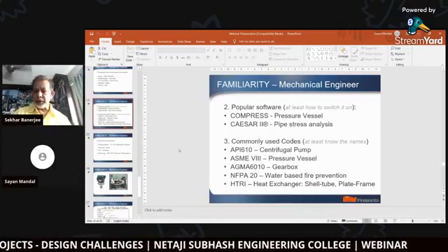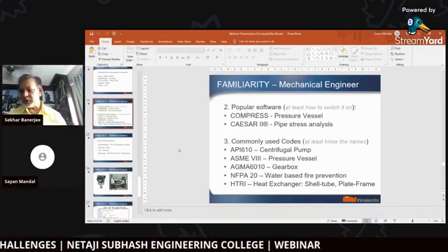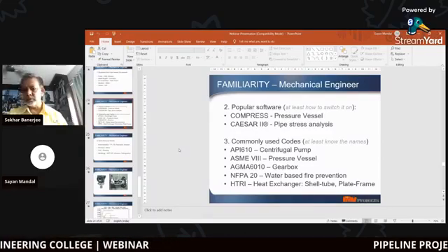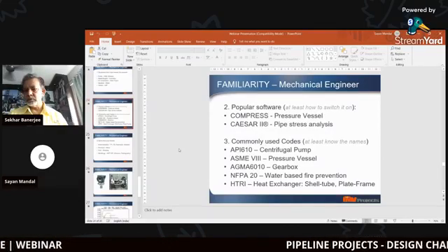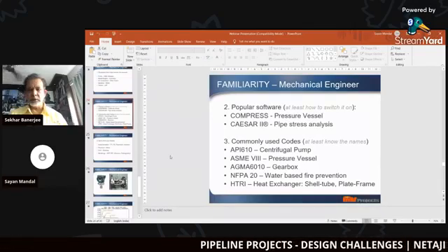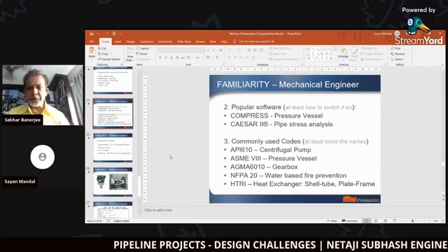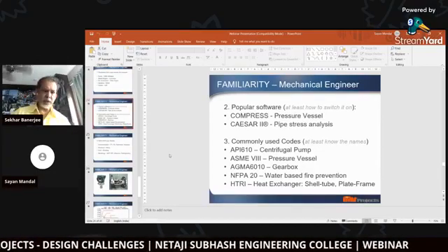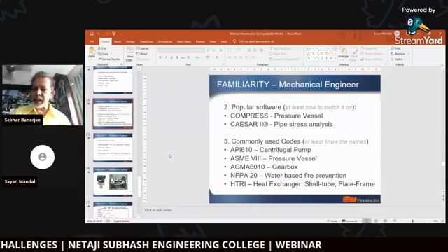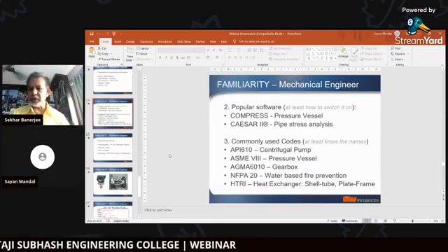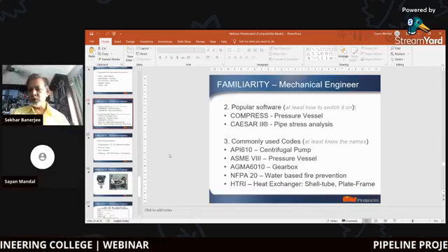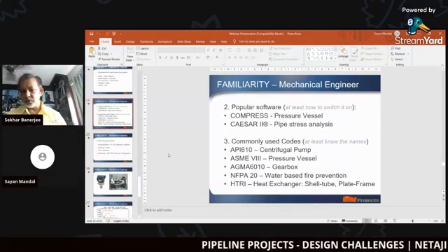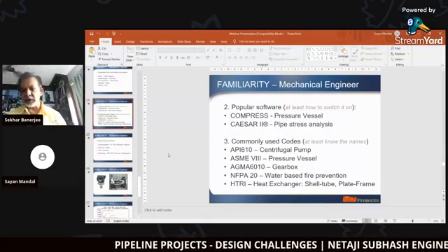And for firefighting, again, fire is fought by water, right? So can you take any pump from the market? No, you cannot. The building or fire department will not give you a license for that. That pump has to be approved by NFPA 20. That's the same single stage cast iron pump. It has to meet a few additional requirements of NFPA 20. Do you know what NFPA is, the National Fire Protection Association's code? We just need to know the name, nothing more than that.